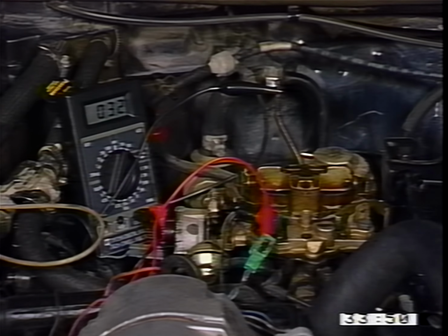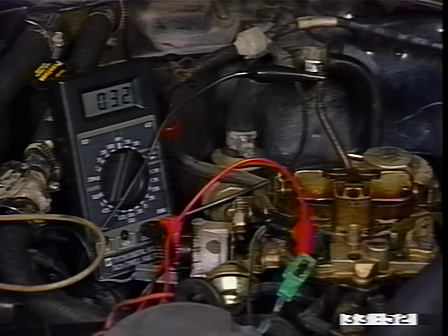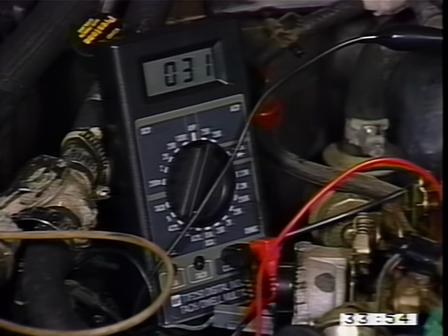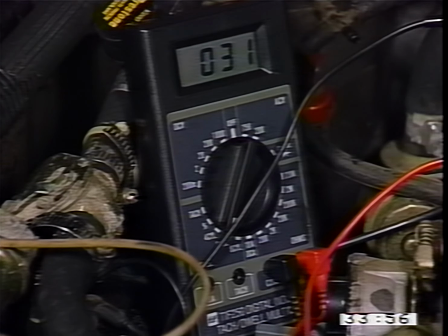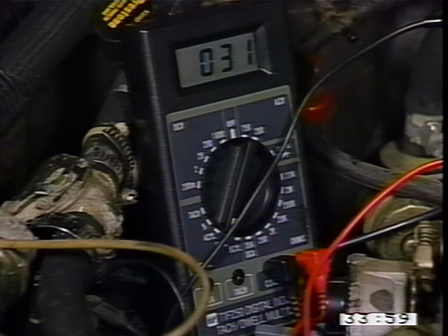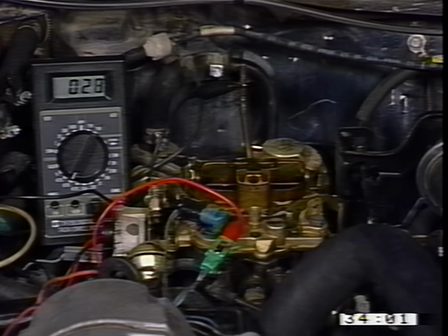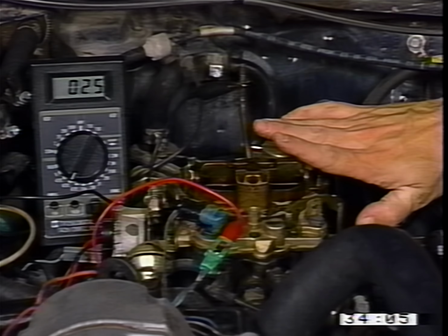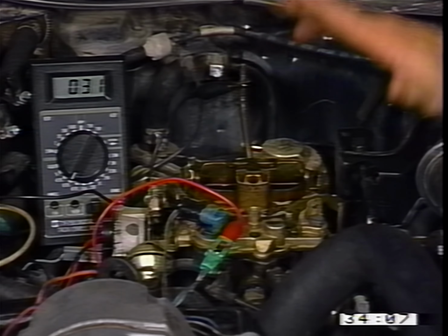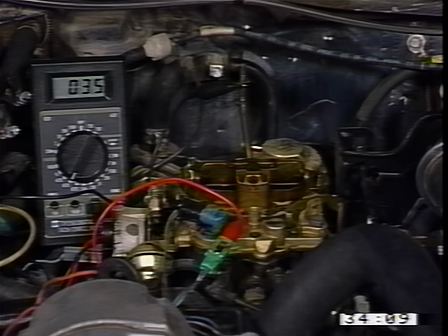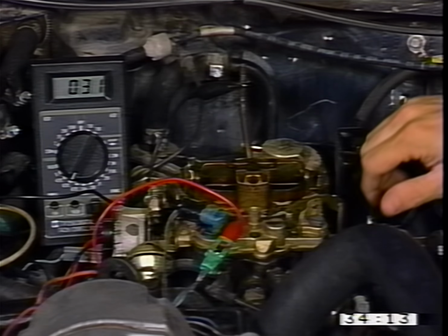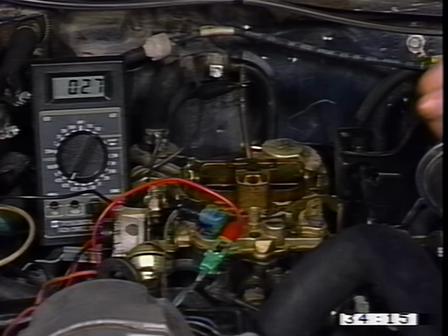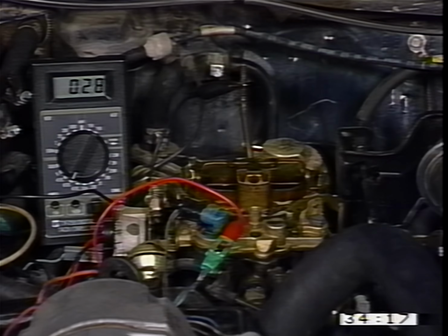Dwell should be fixed between 10 and 50 degrees prior to the engine getting up to operating temperature, which signals that the system is in open-loop operation. The dwell meter should, with the engine idling and at operating temperature, vary between 10 and 50 degrees. The carburetor is set on the high step of the fast idle cam and run for a minute or until the dwell starts to vary, whichever happens first. The engine is returned back to idle and the dwell noted.